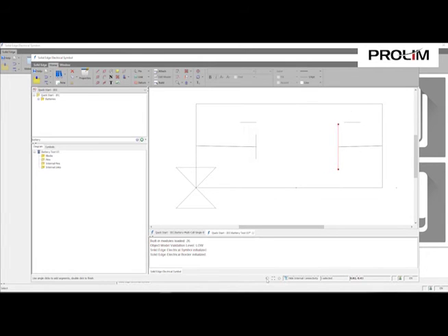So I could just go down here and toggle on and off object snapping and my snap to grid features, so I can get a little bit more control. So you can see now I'm not snapping to that middle point. And there you can see I very quickly created a generic symbol here. Nothing fancy, but just so you understand the actions here. Now, if there was some sort of logo or something here, I have the option to attach that.